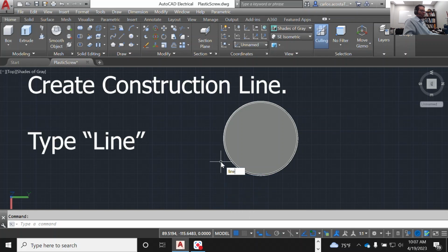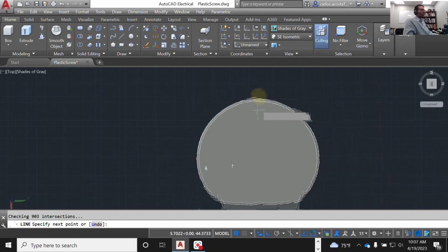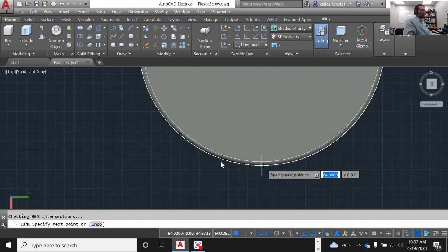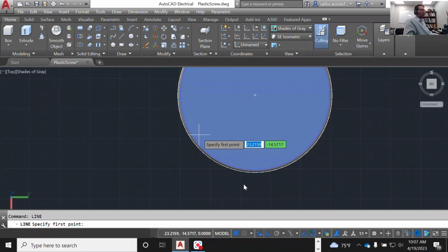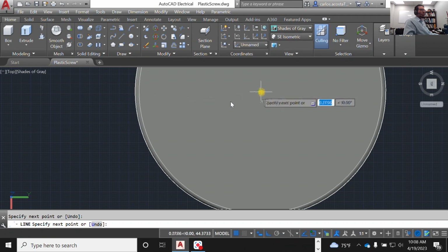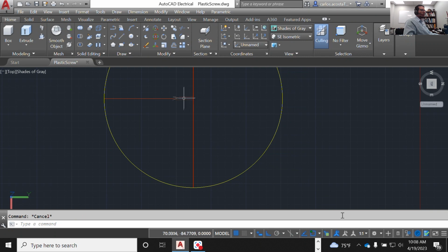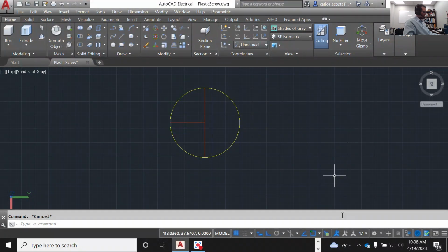create a line to help me build my center line again, since I was not able to put my coordinate system on right at the center of the top surface. So that's not a problem. I can just go ahead and create that set of lines. So if I click on the object and I hide it, then I have a set of lines with a center point. And I need that because I'm going to create another circle with diameter 22 millimeters,